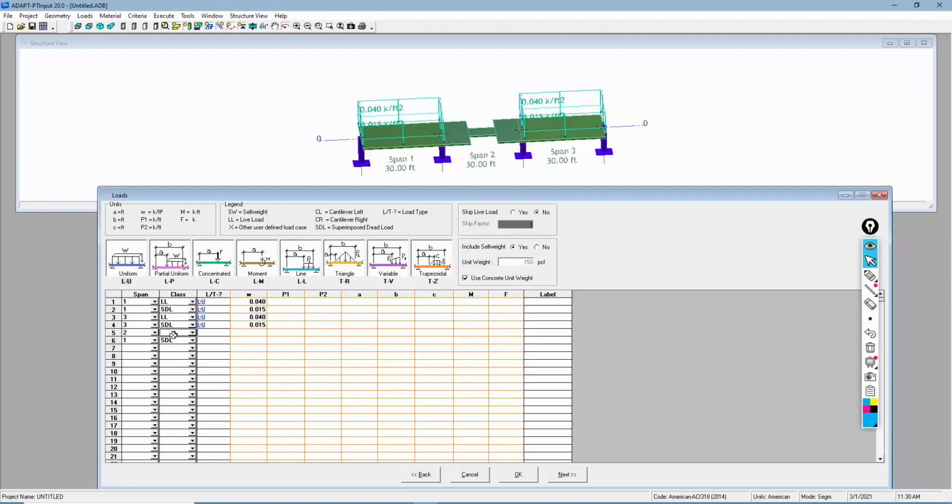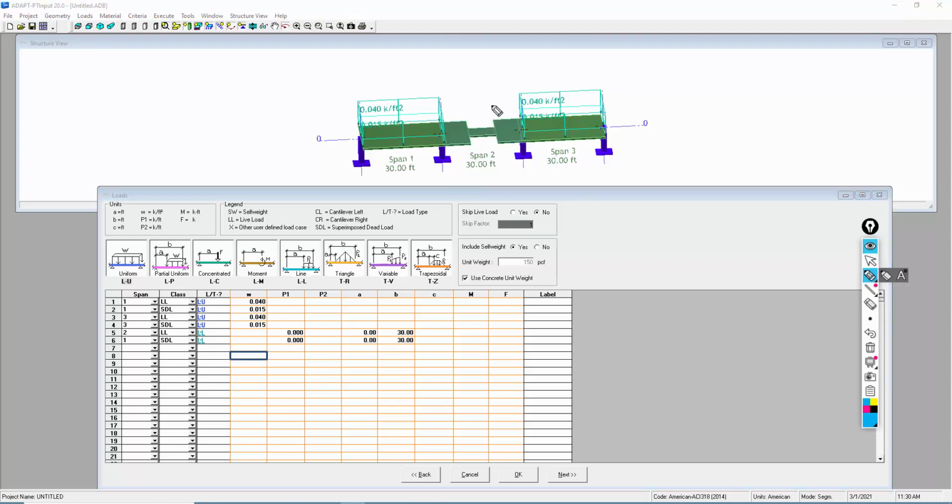We're going to say that for live load, we're going to actually use a line load for both of these. And we'll say for some reason, because these openings are here, there might be some stairs that are kind of coming up into this slab, and they're putting a line load here and maybe here. And those line loads are actually going to be represented on the center line, the reference line of the frame. But we'll make all of the loading for span 2 equal to a line load within this realm right here. I'll talk about this segment and this segment here in a moment. But for this internal segment, we're going to do something a little different.